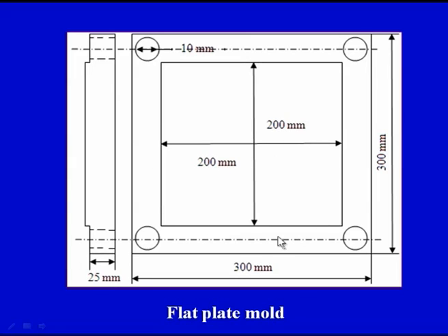The layup would be done here in the form of alternate layers of resin and the reinforcement. The reinforcement, as we have taken as an example in today's class, is in the mat form or the cloth form, in which it is a continuous reinforcement. Fibers are in both x direction and the y direction.